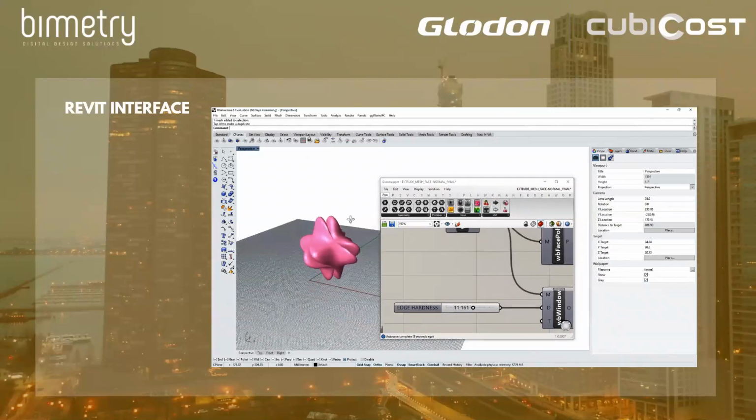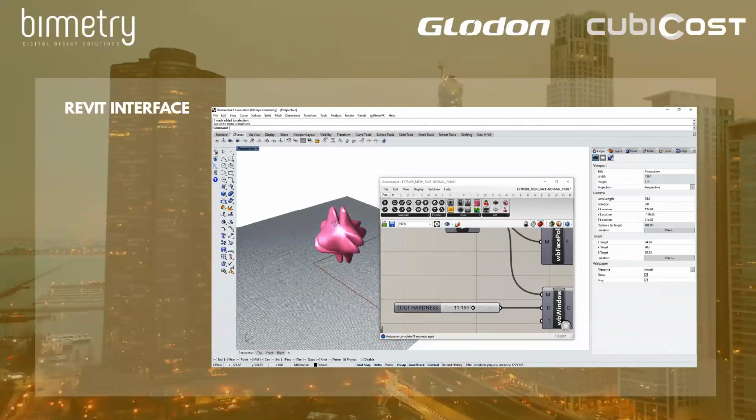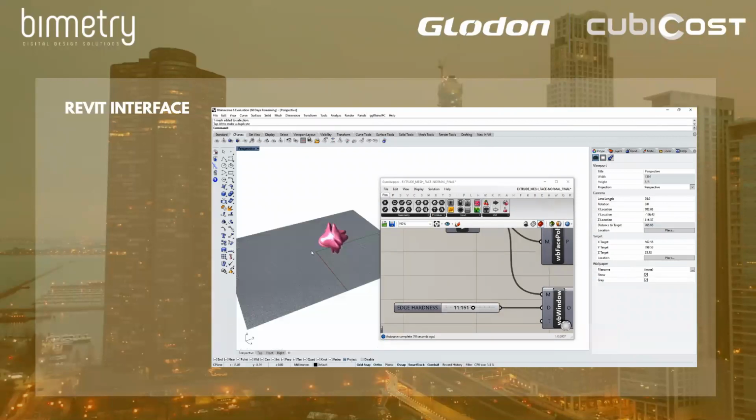So I'm just giving you this tip. If you see some sort of a project which has a lot of curves and organic shapes, you immediately might think that part of it has been designed not using Revit. And this is the moment when you could ask if this geometry has been transferred in Revit and if it's actual BIM or if it's just geometry. Just because if you want to rely on the models to get quantities, you want to know what is pure 3D and what is actual BIM.